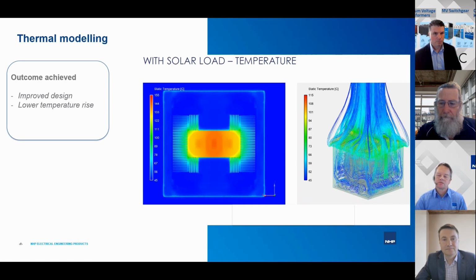testing, and provide us information about the watts loss of the transformer and the oil temperature. And we can build that into the model, because we can run this model on an unenclosed transformer and an enclosed transformer, and that comes back to this class rating. If we run the same model under the same conditions, we can see the difference in temperature, which equals your class temperature.